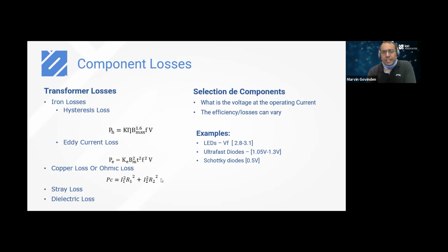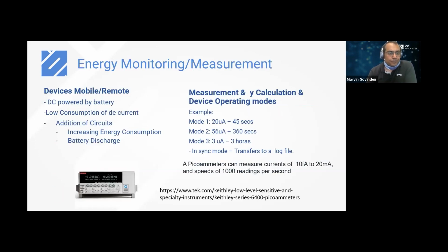And also in my circuit, I could have diodes there, but I could say, well, I'll take out that silicon diode and put a Schottky diode there. I'll have less forward voltage, and that will reduce that power consumption and the heat dissipation on that device. So we can start looking at the voltages that we can reduce in those parts of the circuit and increase the efficiency. Especially when things are running hot, the voltages tend to increase, there's more heat dissipation, and we start to get more losses at higher temperature. So we can start looking at how to reduce those power losses.